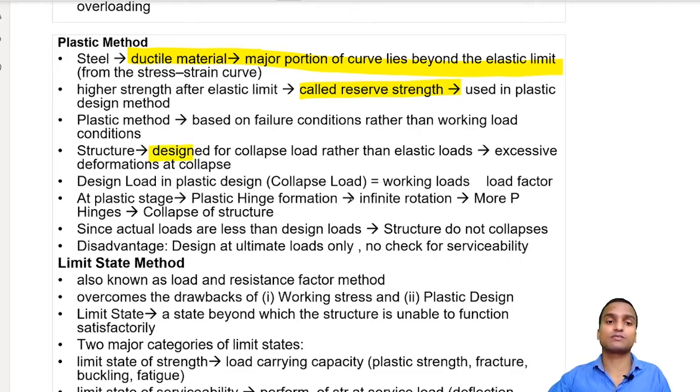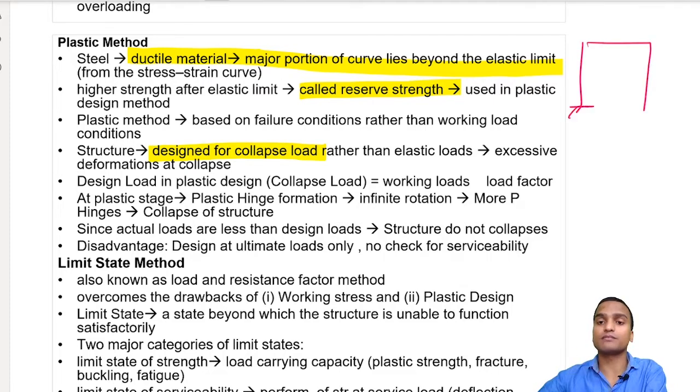load is reached. And what is this collapse load? Collapse load is the ultimate load which comes on the structure and which can form a mechanism. Okay, this is a frame. The formation of hinges has happened, and when we apply a load, there is a formation of mechanism. Now the structure has, on the 4 hinges actually basically, and what has happened, the mechanism has formed.